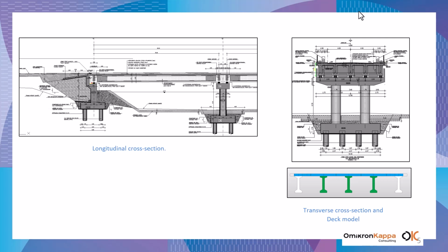The pile cap is concrete and the depth is 1.7 meters. And we have 8 reinforced concrete piles of 1 meter diameter and 10 meters length. Here also we can see how the bridge deck is modeled.